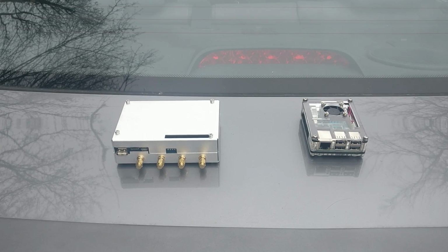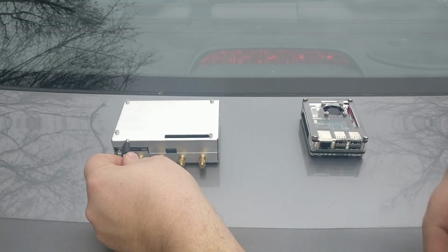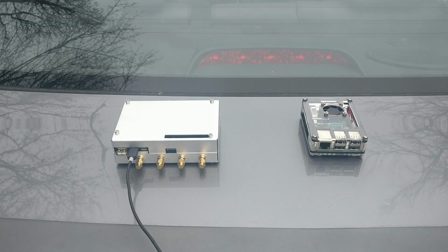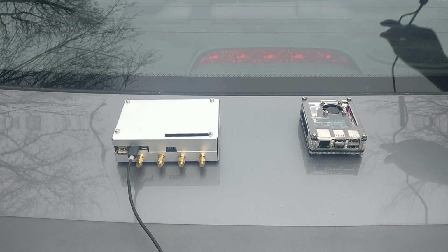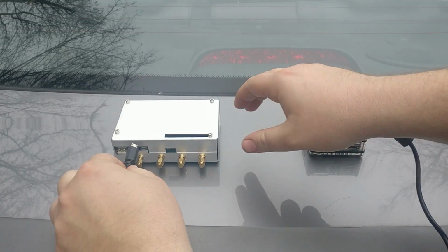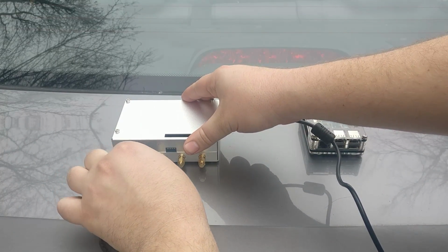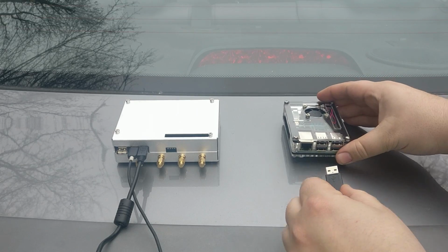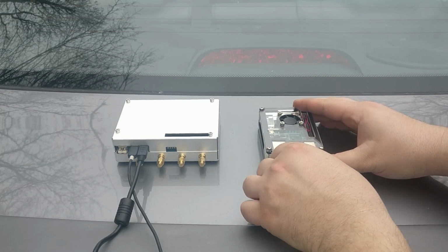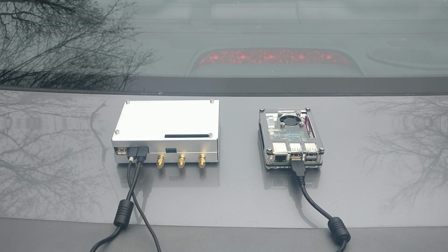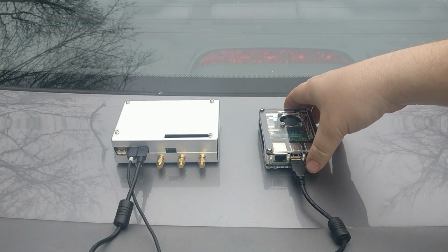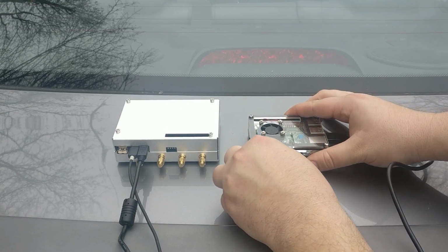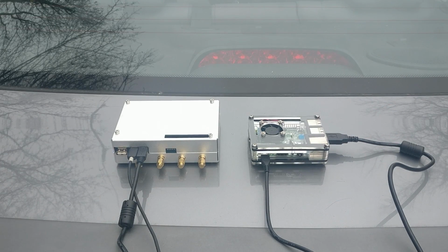Before we begin using the KerberosSDR, we need to go ahead and power it up with our USB-C cable, ensuring that you're able to pull enough current to keep it up and running properly. We'll also need to take a micro USB cable from our Kerberos and plug that into our Raspberry Pi 3, ensuring that the Kerberos has a few minutes to boot before actually booting the Raspberry Pi itself. Once that is ready to go, we'll connect power to the Raspberry Pi 3, and from here we can begin setting up the software configuration for some radio direction finding.